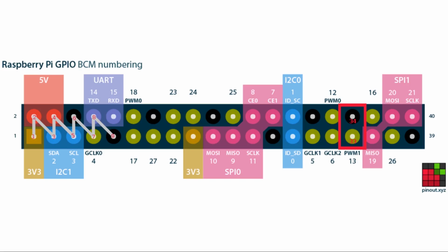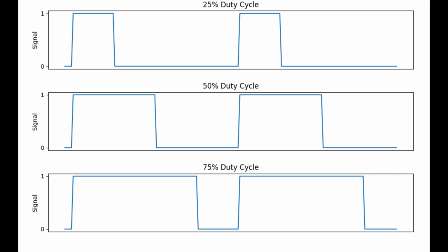The odd numbered board pins are on the inside of the board, and the even numbered board pins are towards the edge of the board. So with this diagram, you'll be looking at the Raspberry Pi holding the GPIO at the top of the Raspberry Pi. The specific pin numbers we'll be using is physical pin 33 for the GPIO digital output, and pin 34 for the ground connection. To generate a digital signal, we'll be using pulse width modulation, or PWM for short.